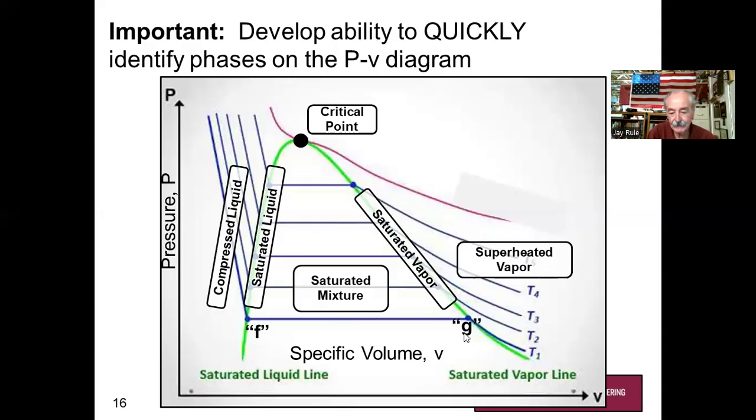When you're on this side of the vapor dome, you're what's called saturated vapor. That's where water's been boiling and boiling and boiling, and all the water's boiled away. It maybe escaped to the surroundings, okay? And all that's left is saturated vapor. You can't even see it with your eyes. It's saturated vapor at the boiling point temperature.